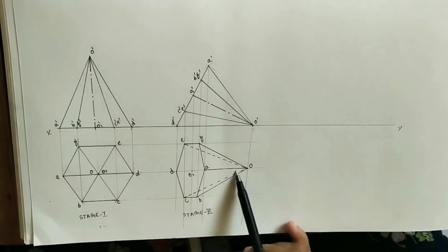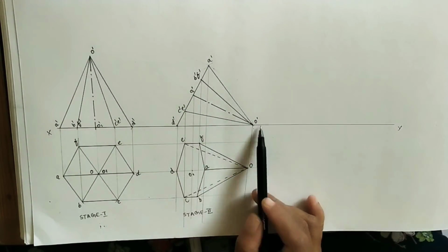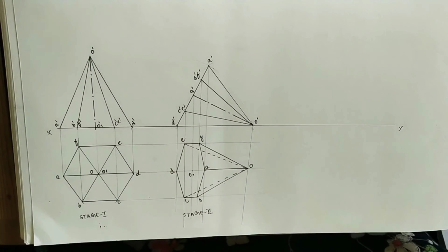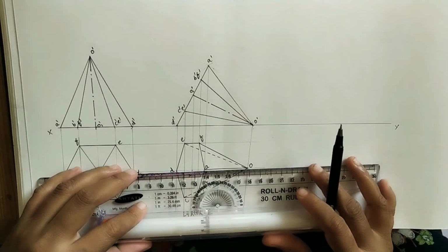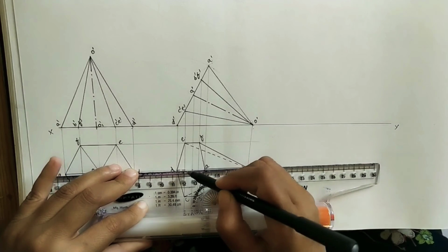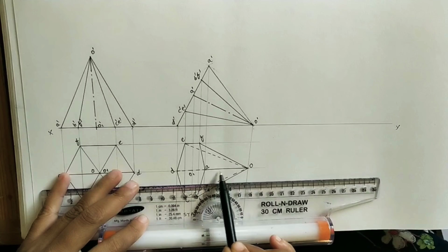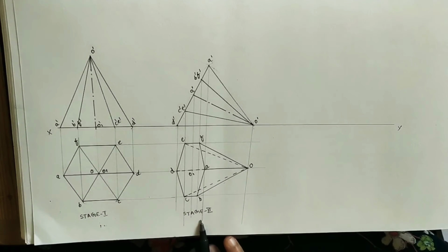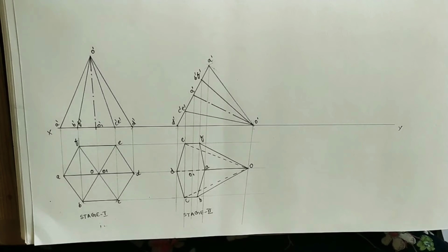After these two, from the top we can't see this edge also because it is on the ground. We can't see OD slant edge. So OD is dotted line. So here dotted line and this continuous line is coinciding. So whatever part we are seeing dotted line, do that one like this, and remaining here also dotted, but continuous line is covering it. It is called stage 2. In stage 2 the slant edge is on the horizontal plane. Let us take the stage 3.